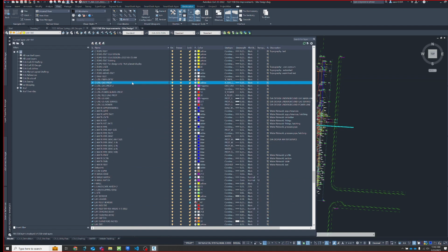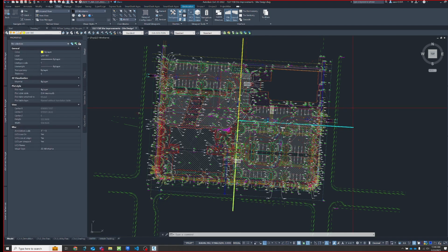So it looks at XREF layers and your external references in this model. If any layer gets added, a brand new one from wherever, you make one, add it from another drawing, copy, paste it, the default thing, if that happens, is that layer goes to off in your layer state. So just keep that in mind. That can be kind of an annoying thing about layer states to keep up on.